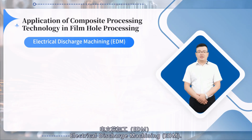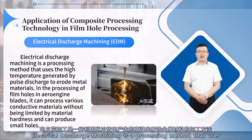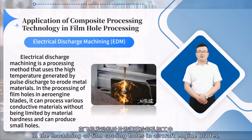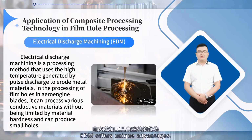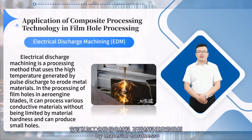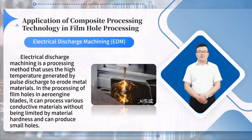Electrical discharge machining, EDM. Electrical discharge machining is a processing method that uses the high temperature generated by pulse discharges to erode metal materials. In the machining of film cooling holes in aircraft engine blades, EDM offers unique advantages. It can process various conductive materials without being limited by material hardness and is capable of producing very small holes.